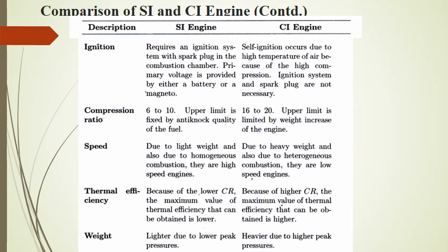If we increase the anti-knock quality of the fuel, it means if we are using a fuel which has better anti-knock quality, definitely it will be an expensive one, but we can raise the compression ratio. But again, there is a trade-off between the economics of the fuel and the anti-knock quality of the fuel.